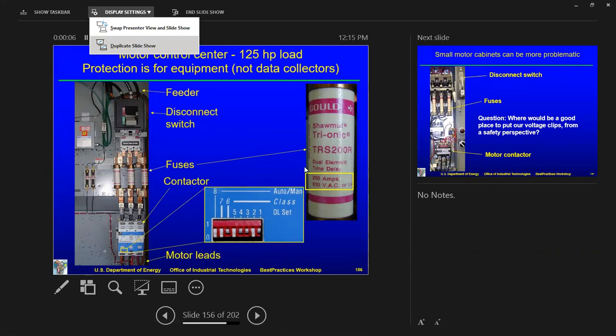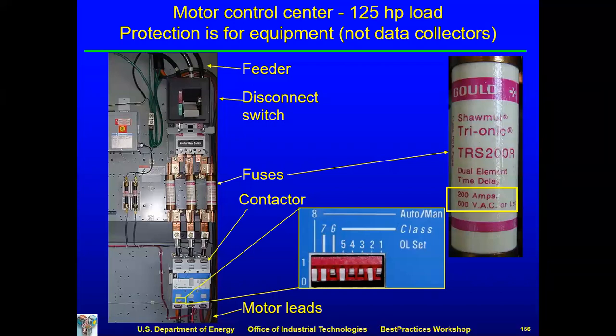Okay, so you see it pretty well here. So you've got 3 wires, 1, 2, 3. Phase A, phase B, phase C. You can name them whatever you want. And if you were going to take power measurements on this thing, you probably come down here where you got a little bit of open wire. You can clip a CT on there, a current transformer, or CT. You can get them that open up, and they call them donuts. You can put them on there for permanent installation.